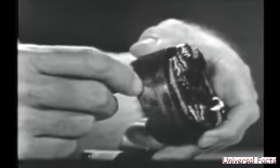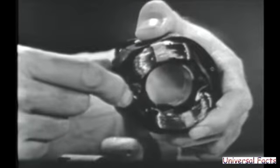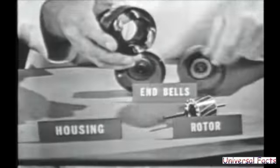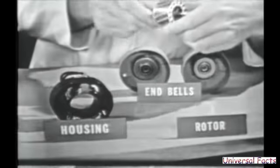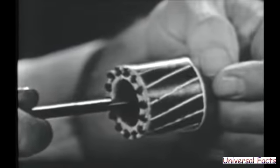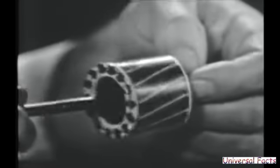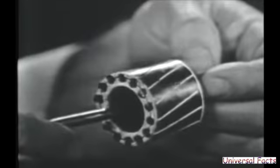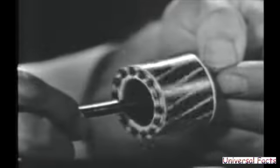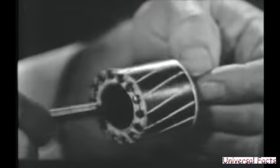Now, notice the simplicity of construction. We have the stator field windings, the iron core. Very, very rugged and very simple. Inside the stator field windings, the rotor. Let's take a look at this rotor. All right, the rotor has no commutator, no slip rings, and no wire windings. It doesn't look at all like the rotor used in DC motors, does it? Not at all. Now, this particular rotor design is called the squirrel cage rotor because it resembles the exercise cages used for pet squirrels. And like the squirrel cage, the rotor is very simple to construct.